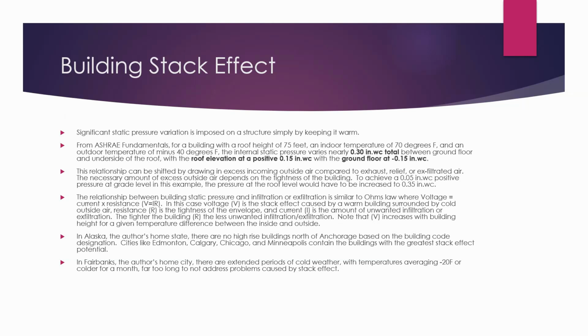The resistance is the tightness of the envelope, and the current is the amount of unwanted infiltration or exfiltration. The tighter the building, the less unwanted infiltration or exfiltration. Note that V increases with building height for a given temperature difference between the inside and outside. So again, just to keep the building warm, you have this stack effect going on.